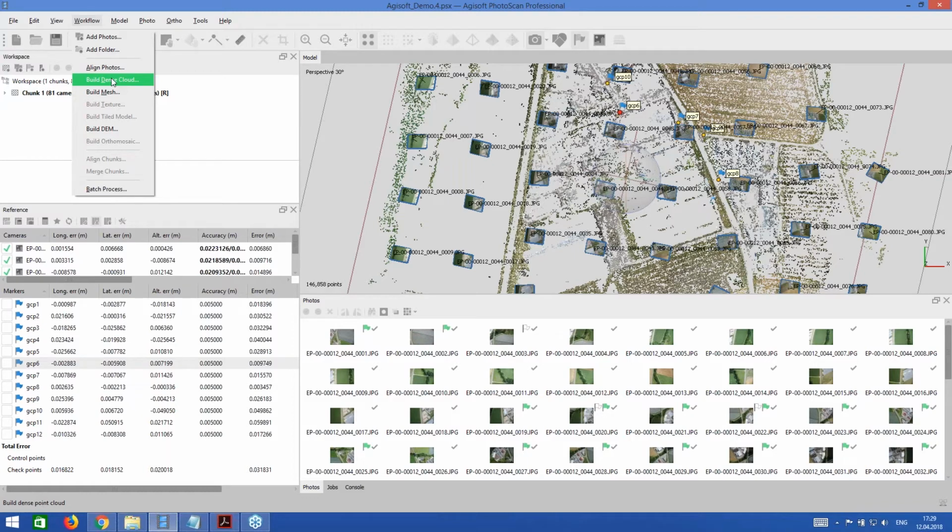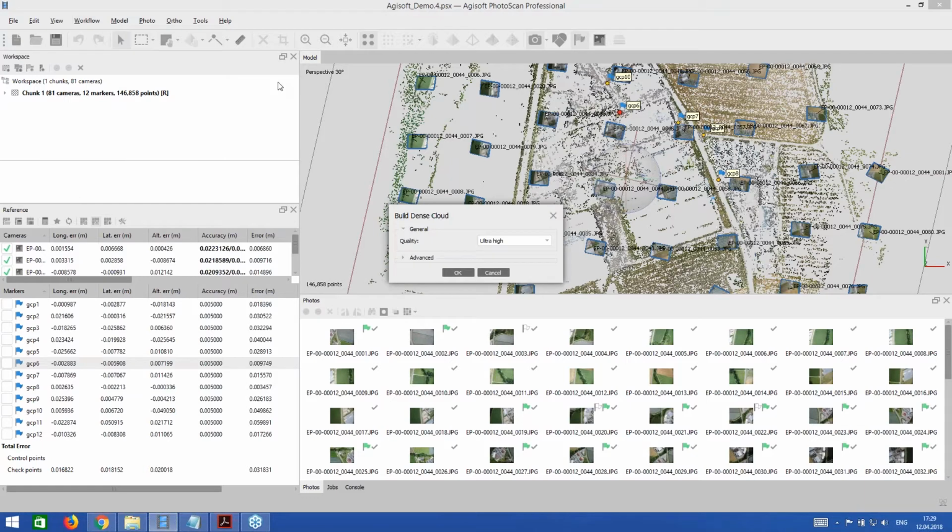Even if it's not of interest to you per se, it is recommended to generate a dense point cloud for every project, since it is the source for an accurate digital elevation model, which normally is required in such projects. The major parameter for the dense cloud building procedure is the quality setting as usual. While the ultra-high setting is appropriate just for some experimental data, high would be the proper option for all ordinary scenarios.